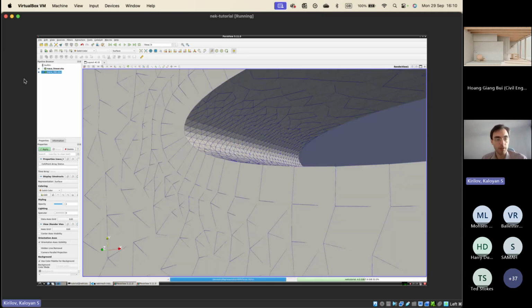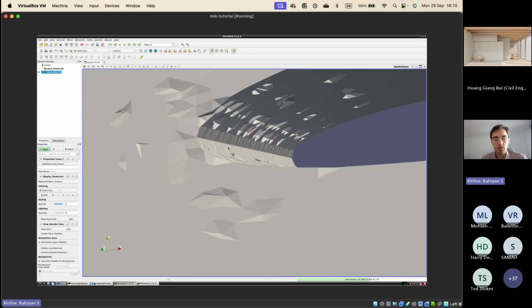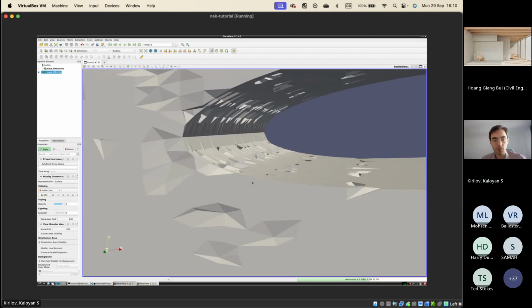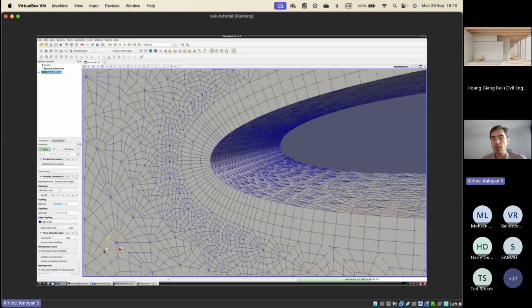And if it's finally ready, in my volume mesh you'll see exactly the same thing here as well. If I show the surface edges, once again, even though this is the high order version before the splitting, you think that you have multiple elements. This is purely visualization, because of using this legacy visualization VTU module that we are having.